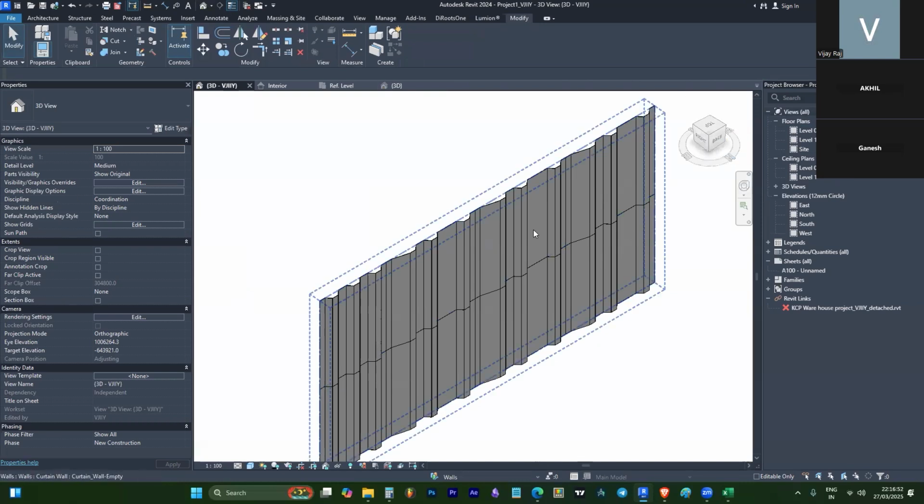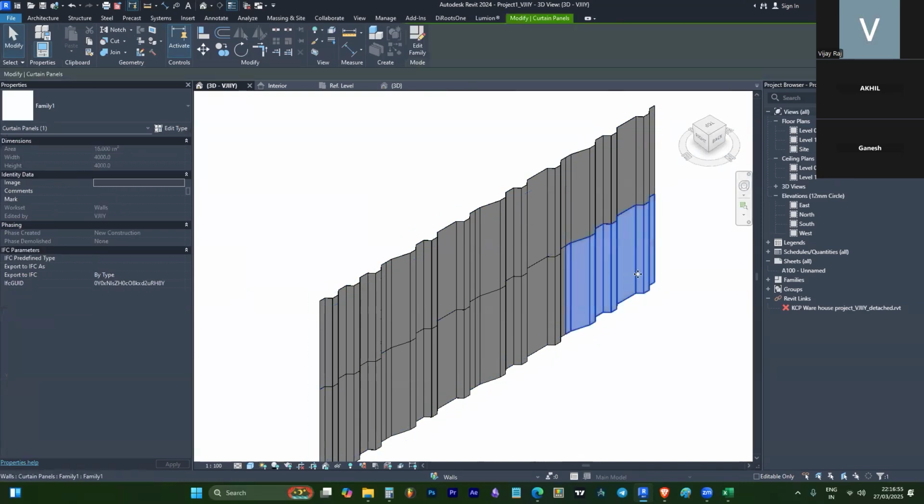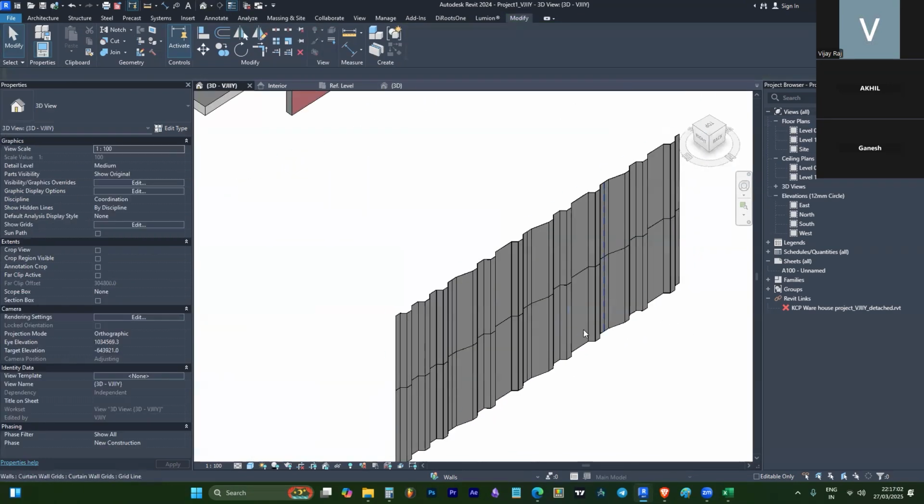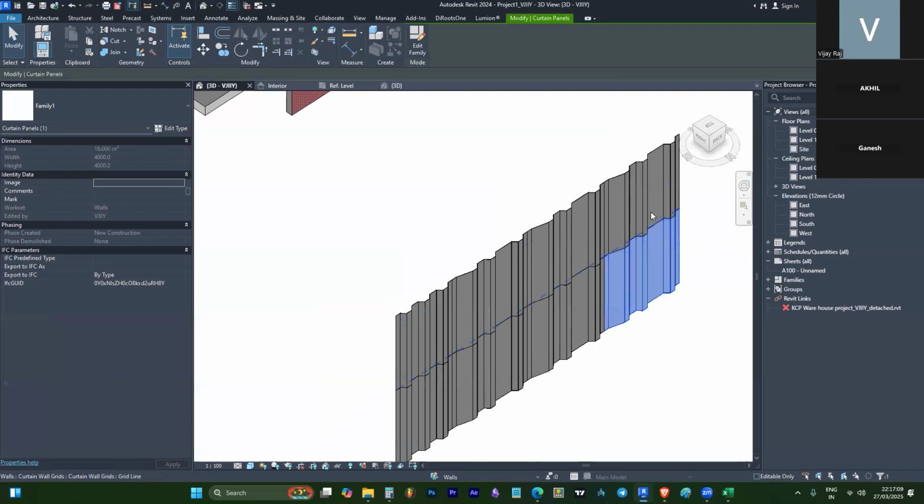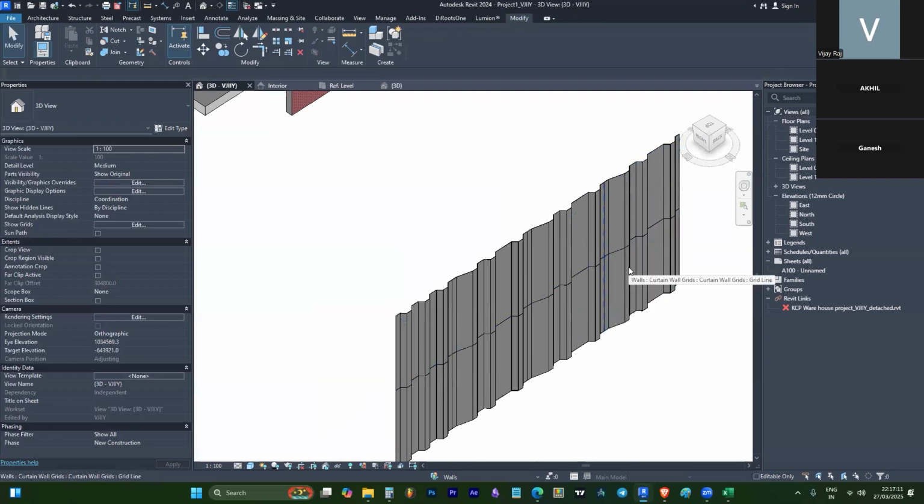First, we draw lines with the reference. You have to get the lines first into the project and cross-check whether it is aligning end to end, whether it is working. Then we will go with the extrusion part to get it without any errors. If you go with extrusions first itself, it may not be perfect and it may not work. So first check with your lines. If the line is working, then you can go with the extrusions.